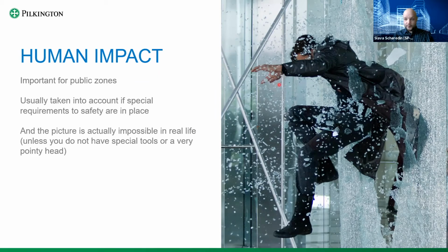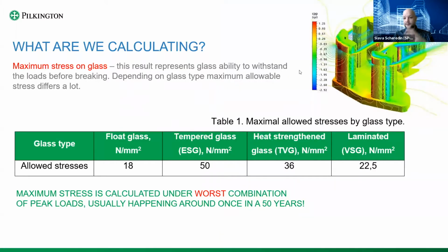Frequently, if we have a big project, the project has a small maquette made of itself, and then it is blown in an aerodynamic tube. So we can derive wind loads from there. I hope I answered your question. So we can either take wind loads that the client is giving to us or try to estimate them on our own.